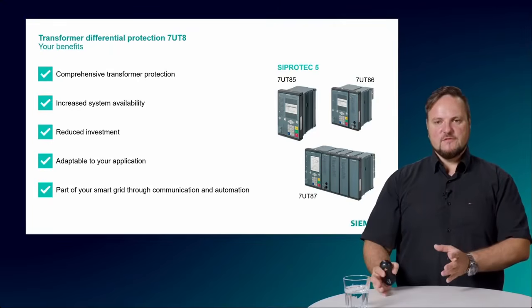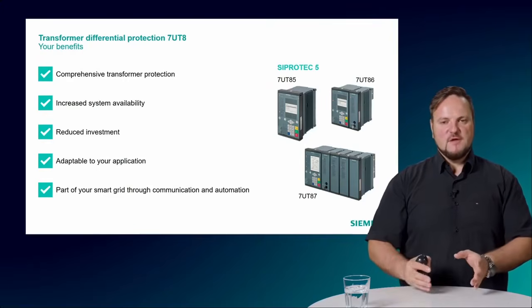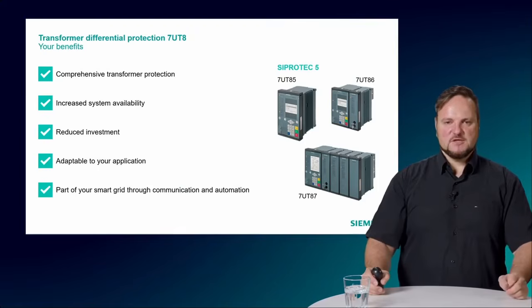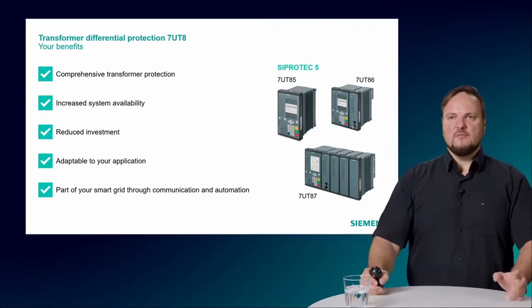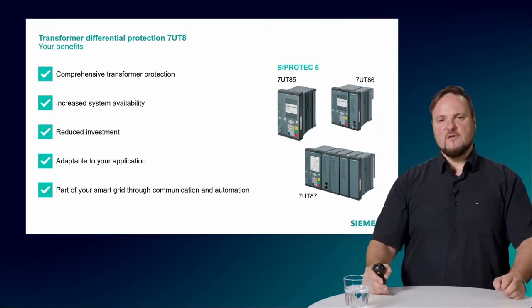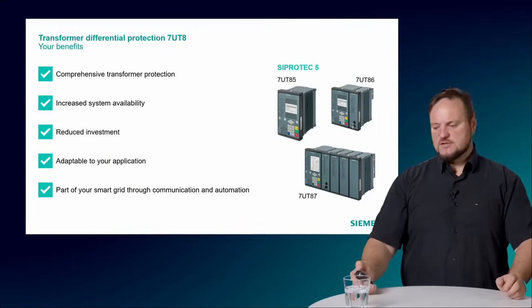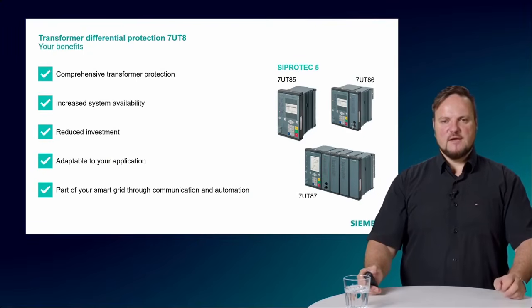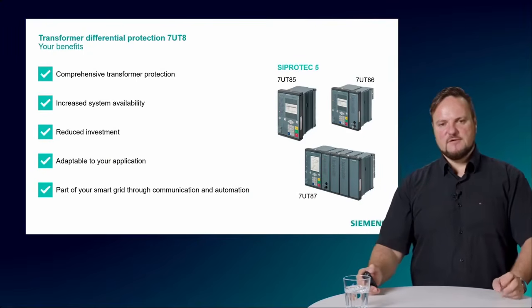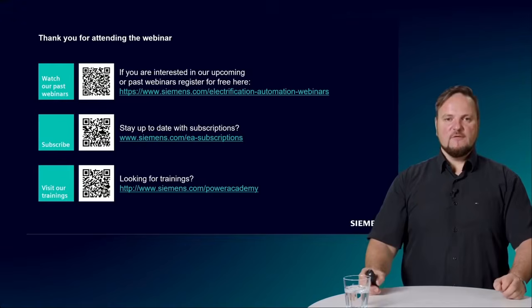That means you can also have this transformer protection device in a digital substation. We support the process bus application, and in the next step we will also support the possibility to connect to LPIT. In the modular series we already have the possibility to connect to non-conventional transformers, and also in the 82 series we will get in the near future the possibility to connect to non-conventional transformers like Rogowski coils or air dividers or capacitive current transformers. And that's all from my side.